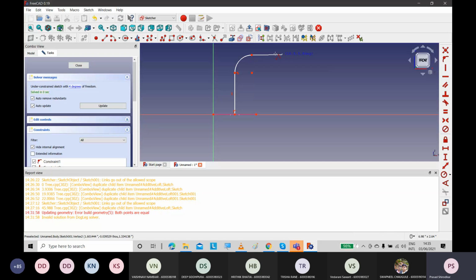Now I want again horizontal line, so again type M 2 times, and again I want circle, quarter circle approximately, select this, again type M, select them, and make sure that is vertical. Alright, so this is the path. Now I will just give some dimensions to this path.